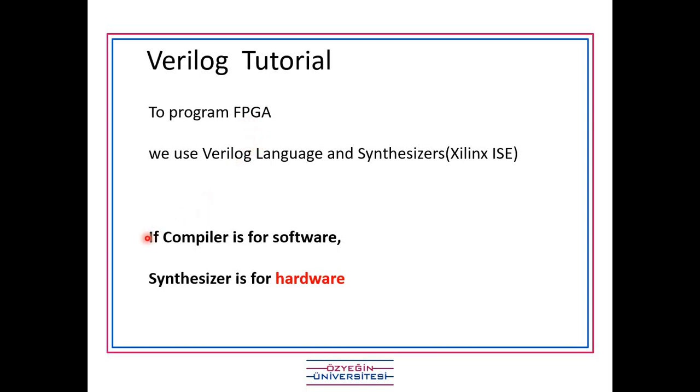And this is very important: if we say compiler for software, we say synthesizer for hardware. That means Verilog is not compiled, it is synthesized. Okay, it's synthesized. Synthesis output will give us LUTs. It will match it into our FPGA, whatever FPGA we have, however many LUTs we have, it will match it into that one.